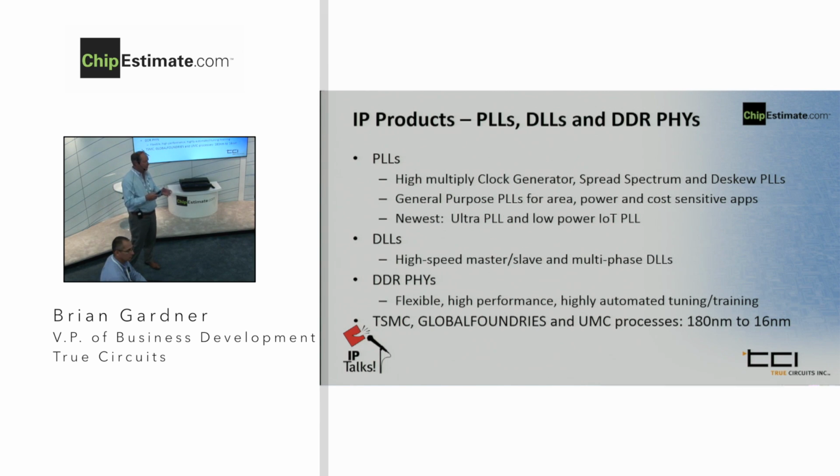So you can not only run at lower power, but by being able to multiply in increments of 32 kilohertz, you can manage your power. You could even turn off the PLL and still have the 32 kilohertz reference clock heartbeat. So, in IoT power, many times it's all about power management.